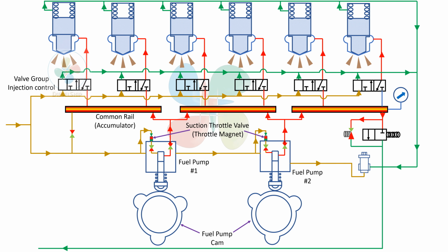So the main functions, I'm going to list the main functions. Please listen to me carefully. When the engine is stopped, it is going to circulate the fuel, right? The fuel has to circulate through the valve group to prevent solidification and to maintain a certain temperature, a preheated condition, right? Like jacket cooling water, fuel also is circulated, which we all know. So this does the fuel recirculation.